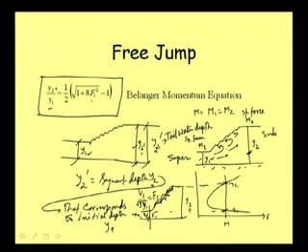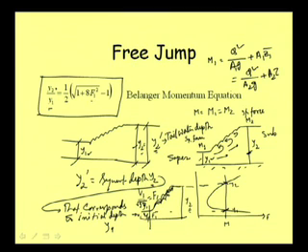How? Because we know that the specific force at this point and that point is equal. Say specific force M1, that we can write as Q square by A1g plus A1 Z1 bar. That we discussed earlier, this is the expression for specific force, and for the hydraulic jump this is M1, and say this is equal to Q square by A2g plus A2 Z2 bar.